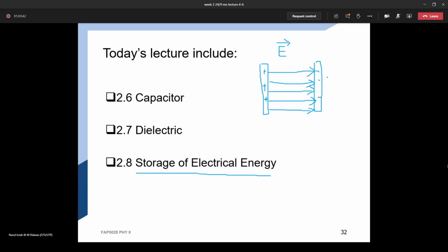If the fan takes a lot of time to rotate, you might need to change the capacitor. There might be something wrong with the circuit. If not the capacitor, it might be due to something else, because there are so many components in the circuit, but it might be due to the capacitor. So that's the function. We need to have the capacitor in the circuit.